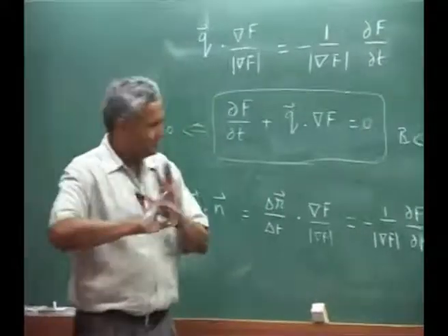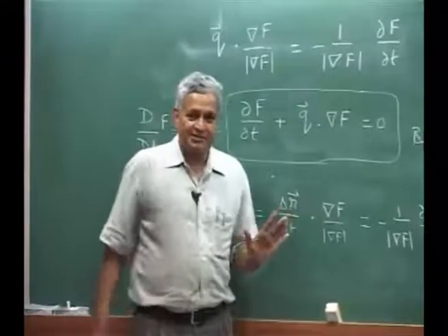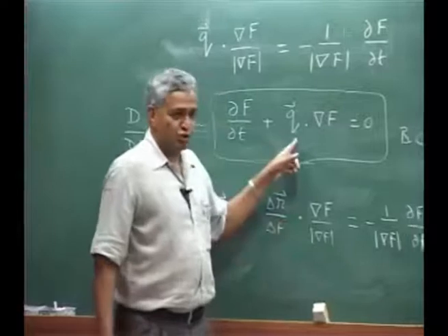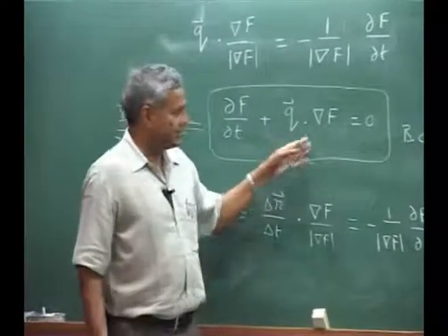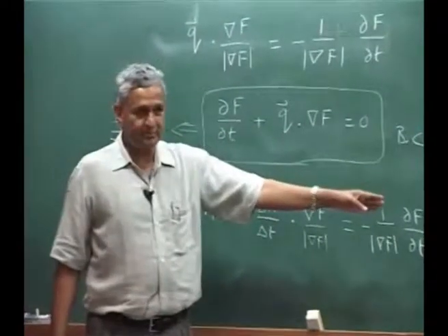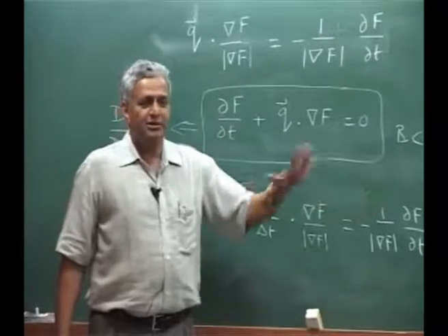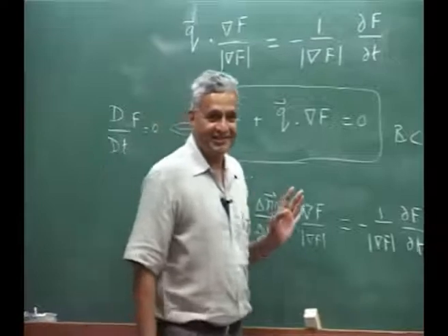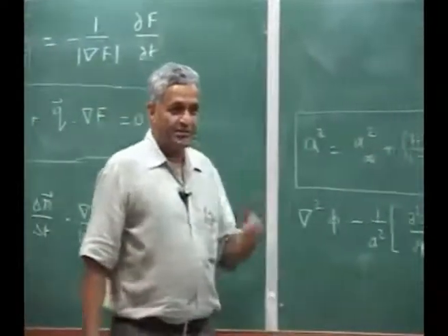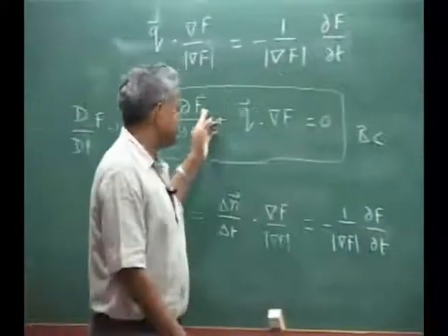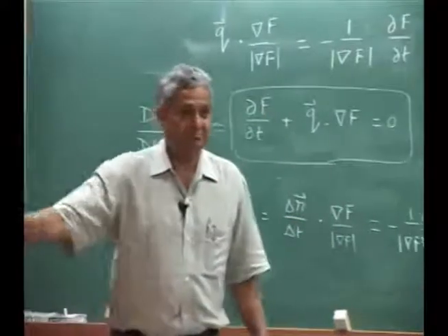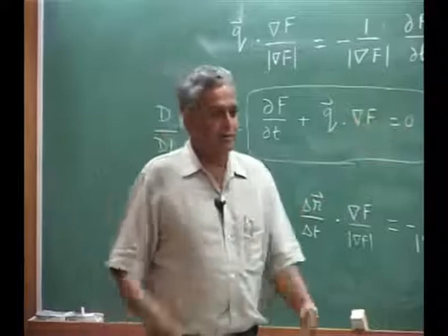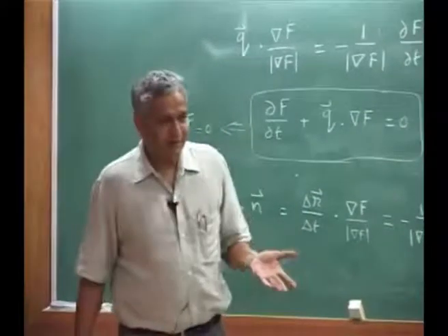Now the whole of unsteady aerodynamics comes down to this, because here Q is nothing but the gradient of the potential. You need to simply satisfy the boundary condition on your surface. Please understand, the surface is moving. F is moving. Now most of the time we will deal with the aerofoil.